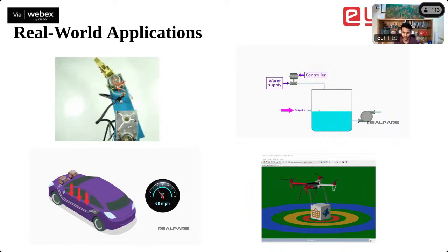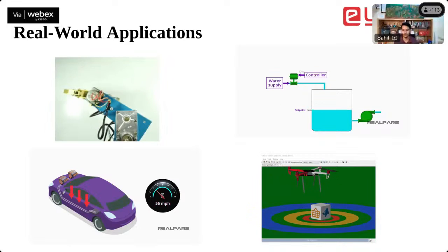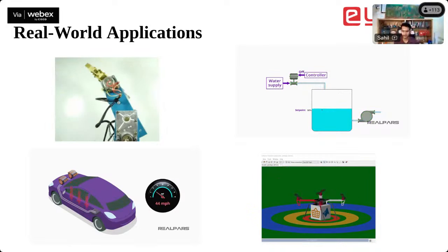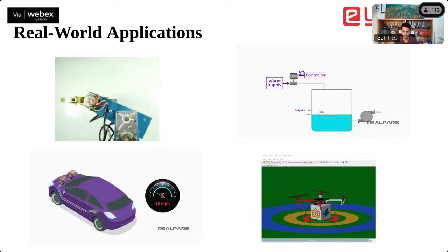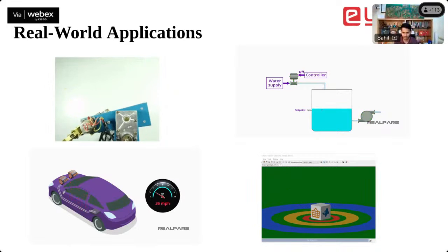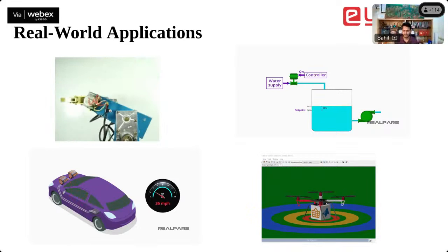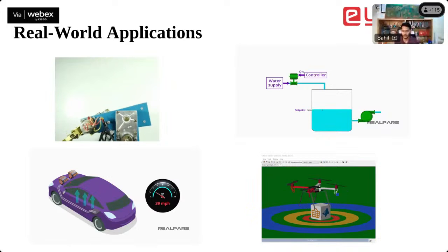Then you add a bit of integral to remove the steady state error. Finally, you add the derivative to reduce the overshoot and oscillation. It's basically like adjusting the bass and the volume of your speaker. There is no perfect setting for that. You just adjust it based on how it sounds. Similarly, PID tuning is part science and part art. So that's how it's done.